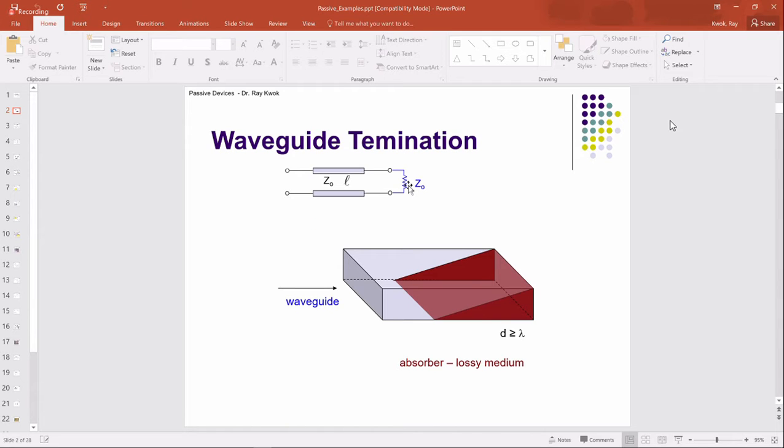So in this way, you have to think in terms of waves. For a waveguide, if a signal is coming in here, you can think of, well, how am I going to terminate this? What does it mean by putting this termination here? It means it just stops the reflection. It means I just want to make sure there are no reflections back to my transmission line.